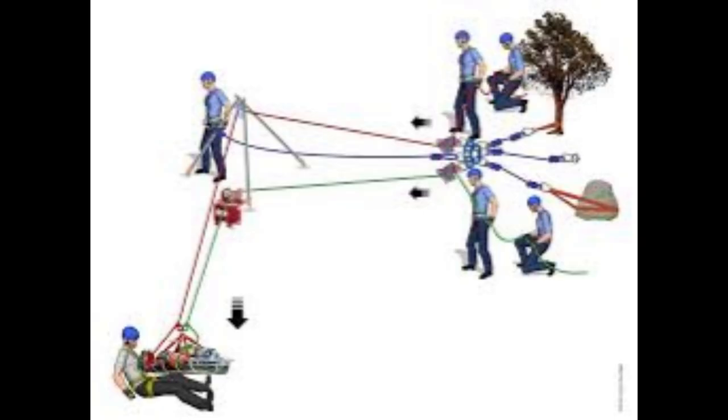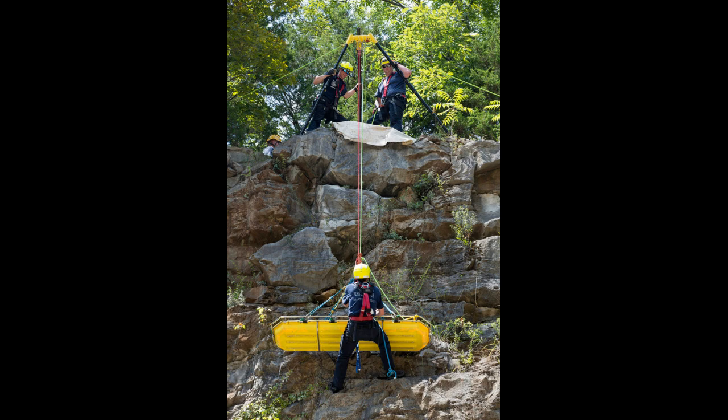Remember, the direction of pull matters. It's one of the main ways vectors shape the system, just like we've been talking about. Here's the takeaway. Everything we've covered, tension, angles, friction, edge protection, works together. If you know the fall line, you can look at a system and quickly spot problems before they happen.